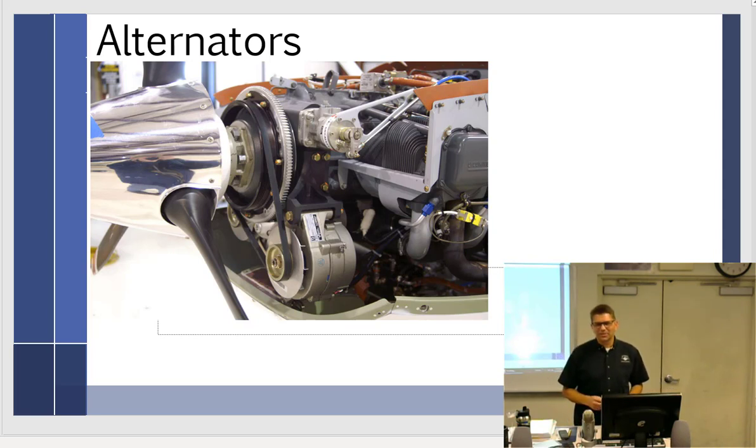Hector probably has a legitimate question. When you put them in, is it hard to line it up? It's an aircraft. Nothing's easy. And then you drop one of the bushings out, and it falls down into the engine, and then you're going to hate your life. By the way, big bore Continental engines have the same style of bushings to drive magnetos, and they're up top, and they do tend to fall if you're not really careful.